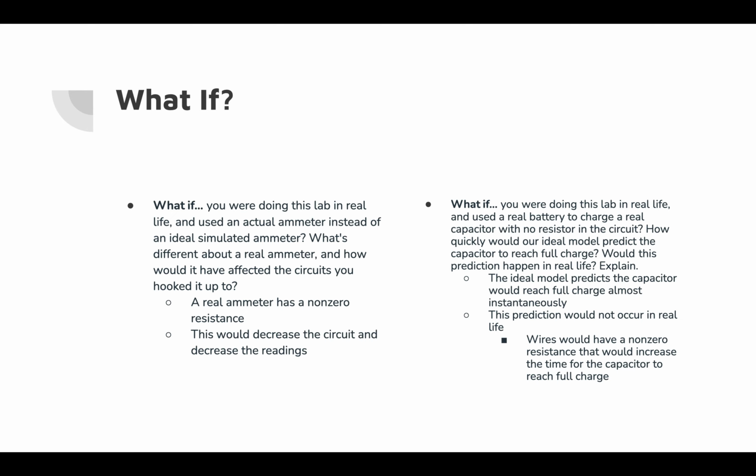So what if we were doing this lab in real life and using an actual ammeter? What's different and how would this affect the circuit? A real ammeter has a non-zero resistance, and therefore this would decrease the current in the circuit and decrease the readings.